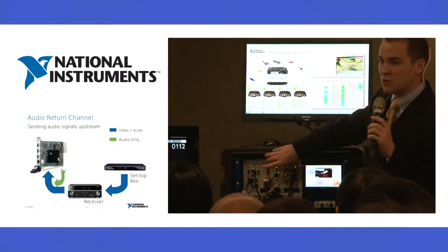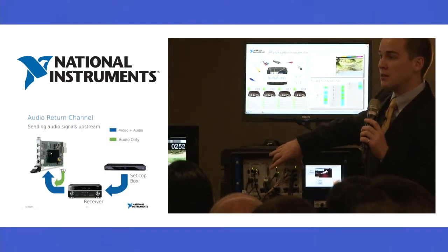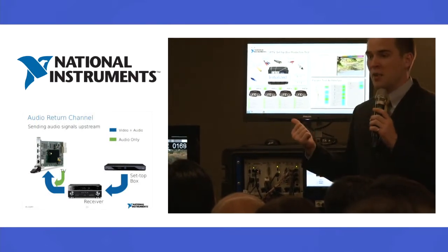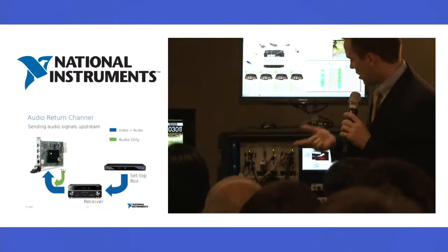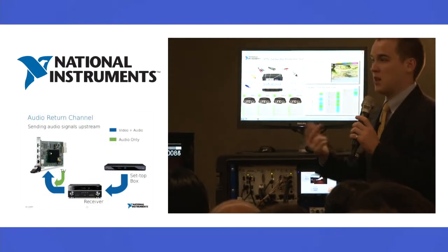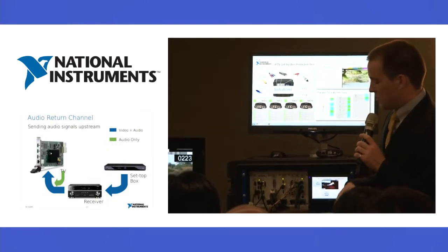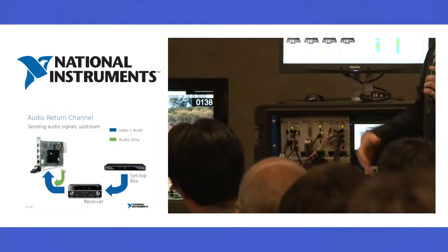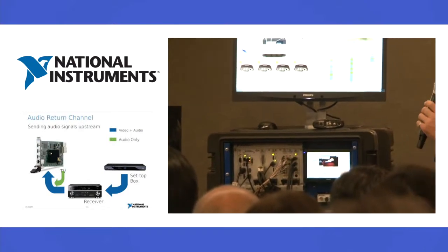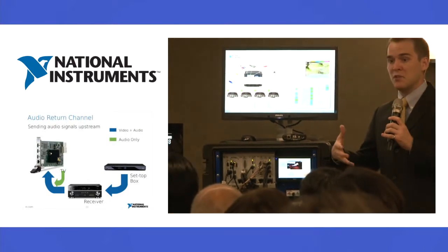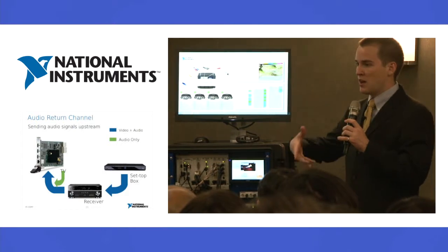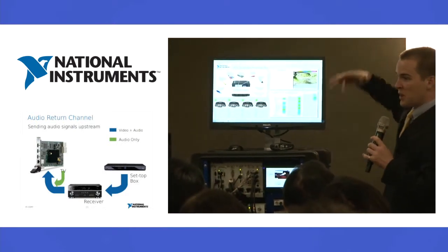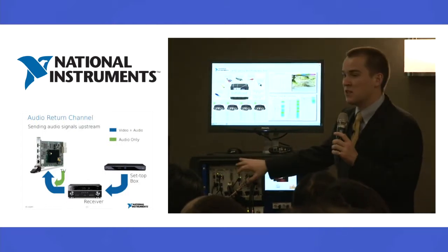And then each of these modules is a different instrument. And the nice part about this is if you need to test HDMI and also test analog audio and also test optical SPDIF, depending on your needs, you just get different modules and put it into one test box. And this is opposed to, let's say, for instance, rack and stack. You have the big benchtop instruments. Well, if you want to test all those, you have a box that's bigger than this for each of those. And you put it in a big rack and you have to move it around. All of that fits in one box here.